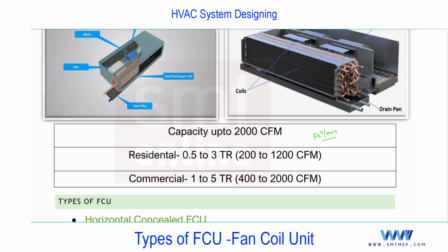So you know there are different parts, as I gave the information at the beginning of the session. One more point here, you can make a note: 1 TR equals dash CFM. I think you know this: 400 CFM. Yes, 400 CFM. This is standard, and it may vary as per the requirement based on the calculation. But from an interview point of view, standard equipment is designed with this flow rate, 1 TR equals 400 CFM.